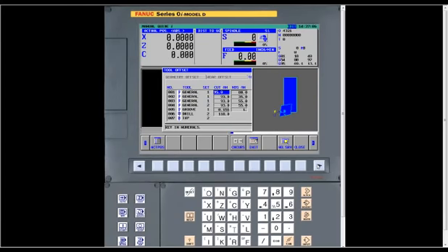All right. Now the next one, cut angle and nose angle. These are very critical, because if we put the wrong information here, you get all kinds of bad information when you actually make the program. As I said, the tool that I have in my machine is an 80-degree diamond tool. And with that type of tool, it always has 5 degrees of clearance on the front side.